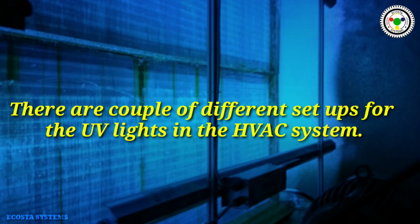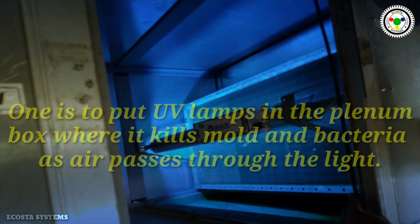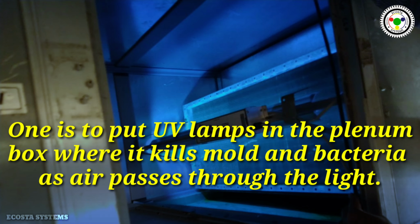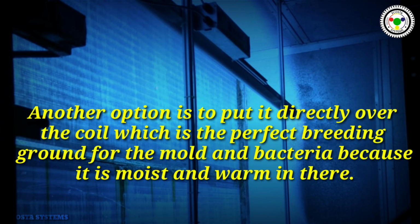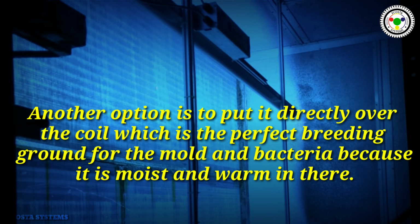There are a couple of different setups for the UV lights in the HVAC systems. One is to put UV lamps in the plenum box where it kills mold and bacteria as air passes through the light. Another option is to put it directly over the coil, which is the perfect breeding ground for the mold and bacteria because it is moist and warm in there.